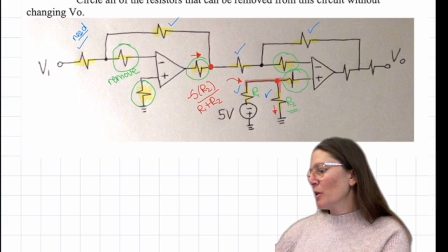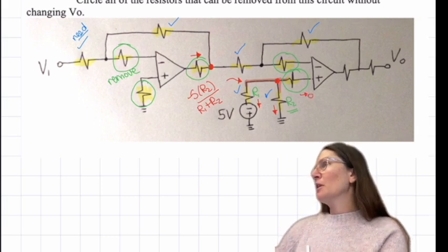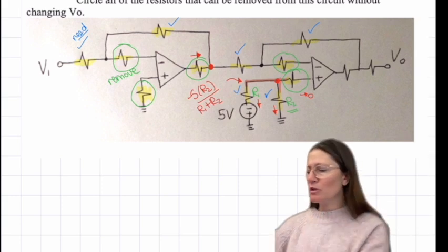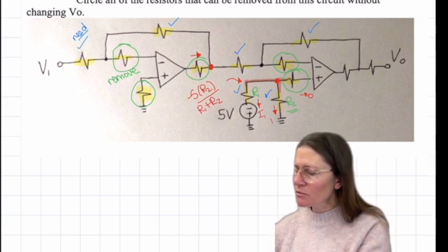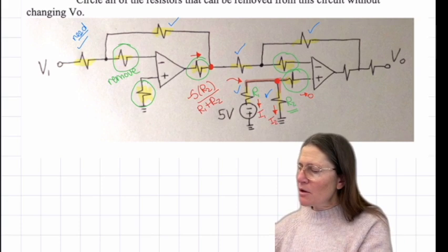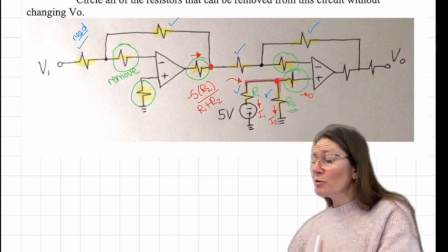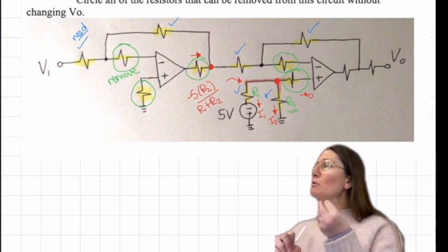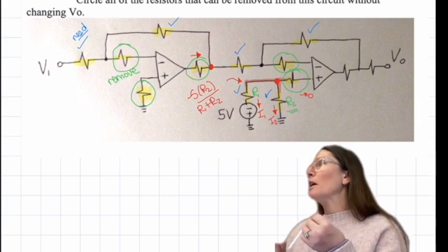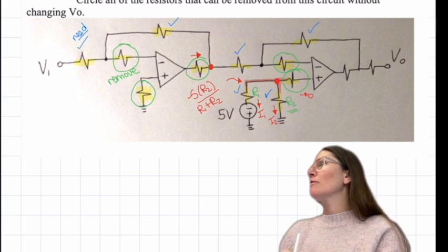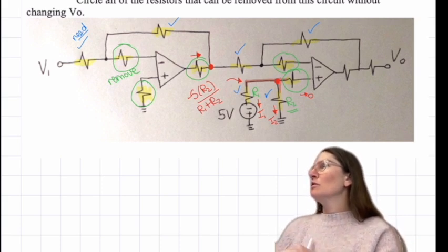So there's current going through here, and there's current going through here. There's no current here. But because there's current going through those other two, I1 and I2, that node will not be 5 volts, but if you removed one of them, it would be 5 volts. So that is a change in that voltage. Does that make more sense? Okay. Other questions?